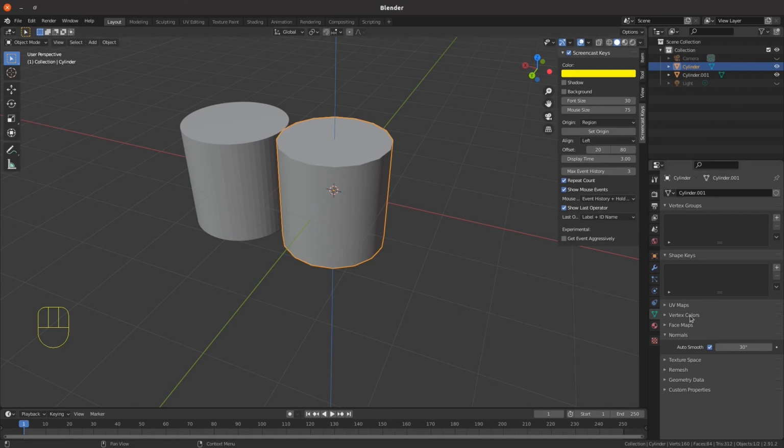So it's automatically worked out that there's very little angle between the outer edges, but the top face is perpendicular to the sides, which is more than 30 degrees, so the top and bottom faces are shaded flat, the rest are shaded smooth. That's one other option that can make it easy as you're modelling, and there are others using edge split modifiers, which we'll talk about as we're modelling in some of the projects.